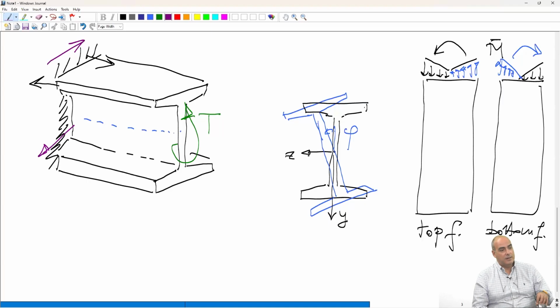So, in cross sections that, as we say, are non-star cross sections, they must not be solid cross sections, and if they are made of thin walls, the thin walls must not converge in a unique point. We have seen in a slide yesterday, you must have thin walls, but they must be separate. There must be a lever arm effect.